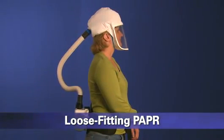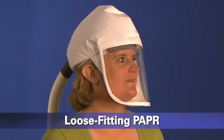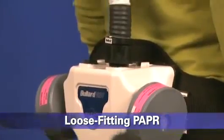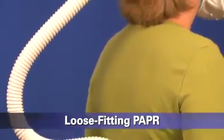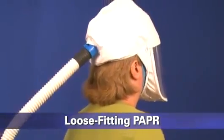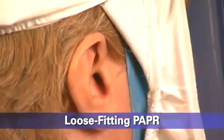This is a loose-fitting face-piece hooded powered air purifying respirator, also known as a PAPR. A PAPR has a blower that pulls air through attached filters. The blower then pushes the filtered air into the facepiece, which covers all of the wearer's face. Since it is loose-fitting, it does not need to be fit-tested and can be used by workers with facial hair.